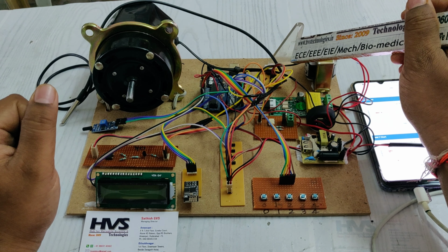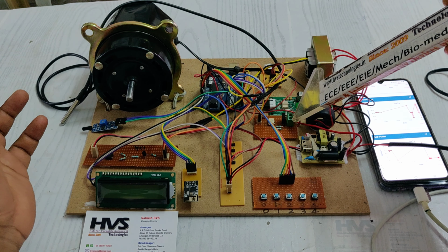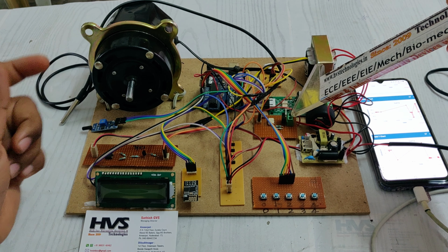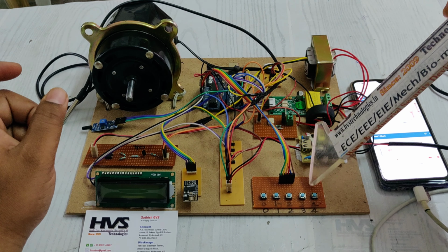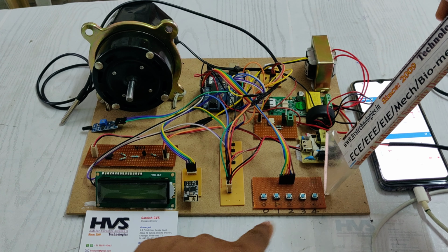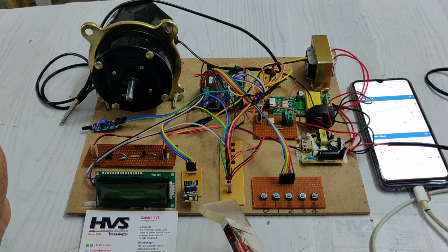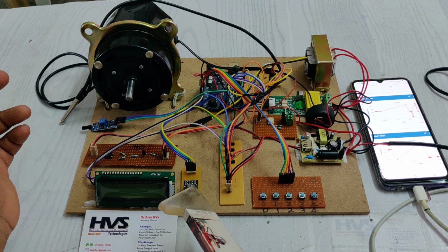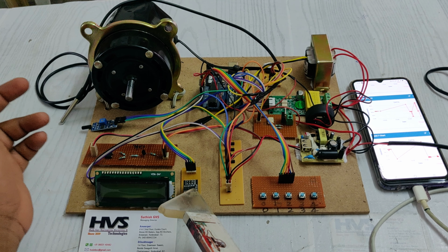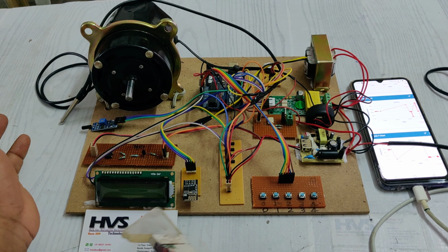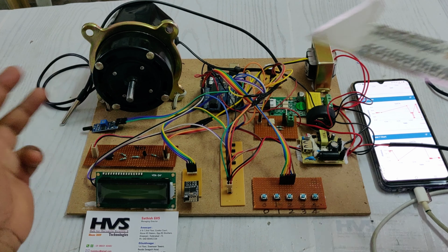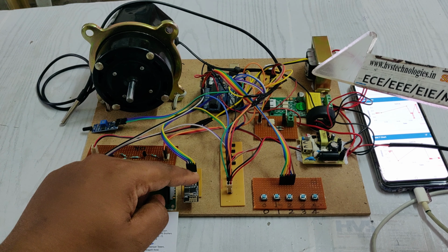And the next is a buzzer board to get audible alerts, and this is the main BT136 triac board to control the switching circuit voltage of the AC waveform. And these are the control switches for selecting 0 to 4, 5 levels of speed, and this is the breadboard to distribute the 5 volts power supply for input output modules. And here is the ESP8266 module. Through this we are going to send the data to ThingSpeak and email alerts as well as Blynk communication. Totally 3 systems are executed in this one.